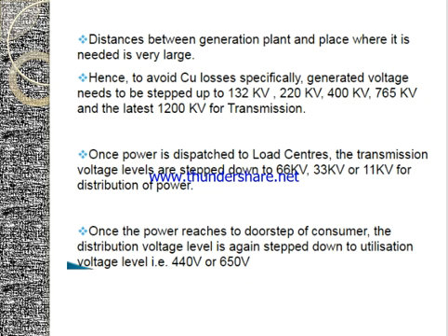There may be large consumers which may directly consume the electricity from the distribution substations, where 33 kV to 11 kV conversion will be there. From primary distribution, they would directly be purchasing the electricity. Other consumers will be connected to the secondary distribution transformers. So these are some of the voltage levels where the generation, transmission and distribution will be taking place.